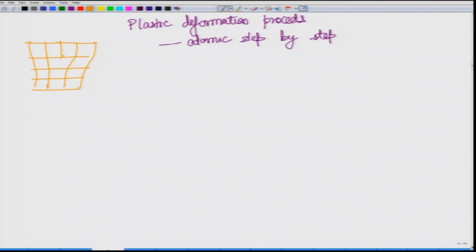Now, you can imagine that this is a dislocation. It is a defect because this plane is not going all the way to the end; this plane terminates inside. In a perfect crystal, this plane should go all the way to the other end. This is a line, because we are looking at 2D. If you go 3D, then this is a line. So, this is a 1D defect, and this is a defect that is first for sure.